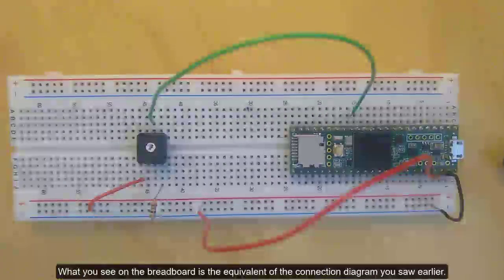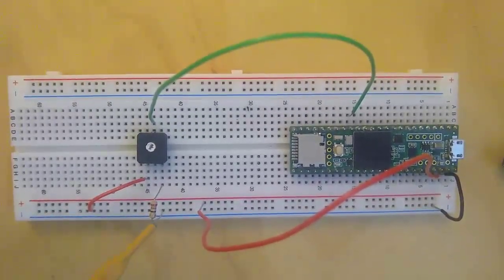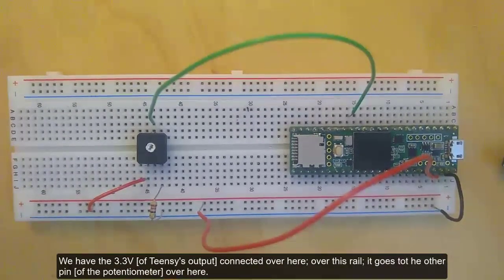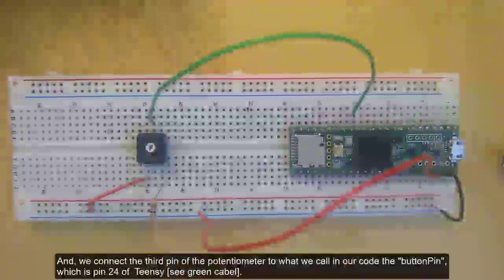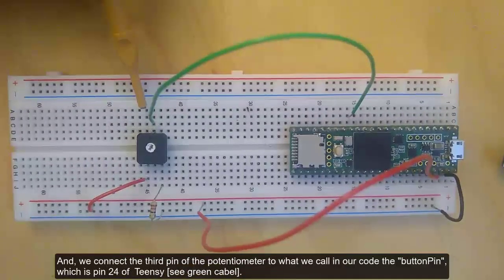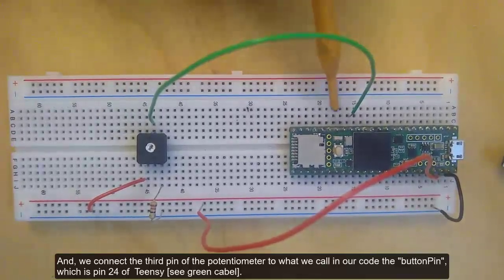What you see on the breadboard is the equivalent of the connection diagram you saw earlier. We get the ground, and then using a resistor, this is where we connect it to the pin of the potentiometer. We have the 3.3 volts connected over here, over this rail, goes to the other pin over here, and we connect the third pin of the potentiometer to what we call in our code the button pin, which is pin 24 of Teensy.